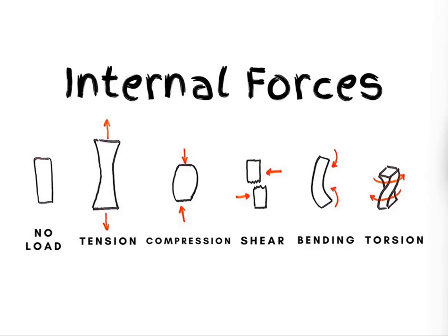It happens when there are torsional moments acting onto the member in the opposite direction, happening at different places of the member. This torsional moment causes shear stress in the member, and this shear stress will lead to principal tensile stress inclined at the angle of 45 degrees to the member's axis.